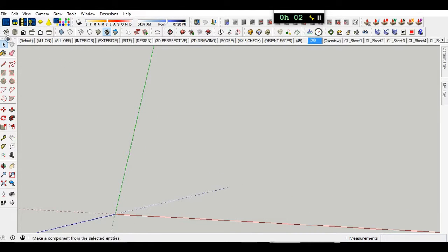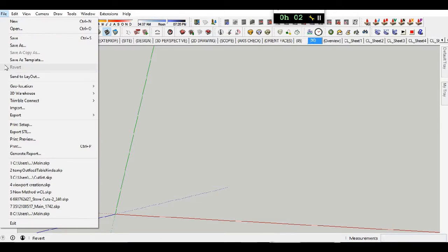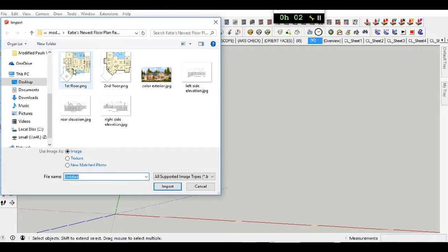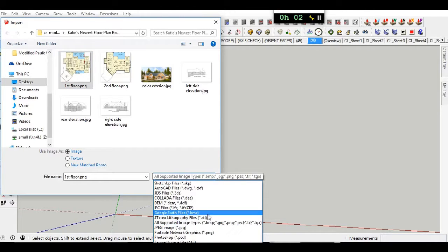Alright, the reason we imported the second one now is so when I come in and resize the model, both of them get sized the same, and therefore they stay matching each other. So to resize the model, when all you have in here is the stuff that you will be making all your size decisions from, you use the tape measure tool.